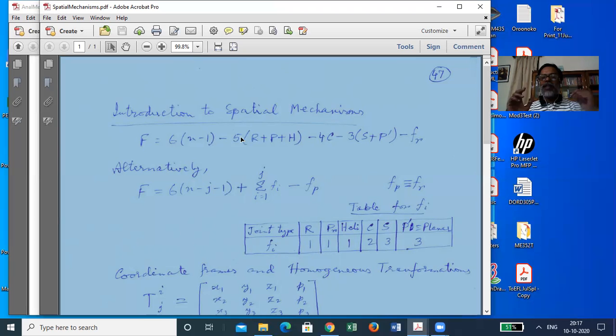They were originally designed to be parallel, and originally were parallel, but after some 37 years have passed, they are no more parallel because links have bent, warped, twisted. So then you find that driving it becomes trouble. Okay. So you try to rotate the input, nothing else rotates, and therefore this also cannot rotate, and a sound comes, right? So that happens because the axes are no more parallel.